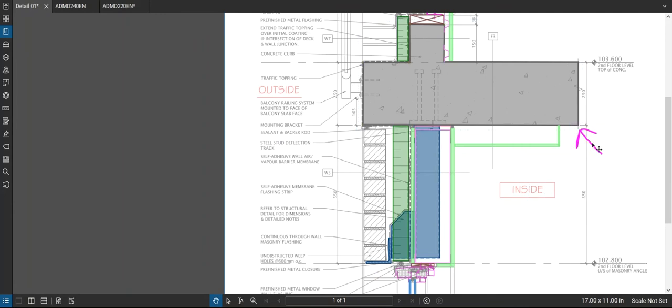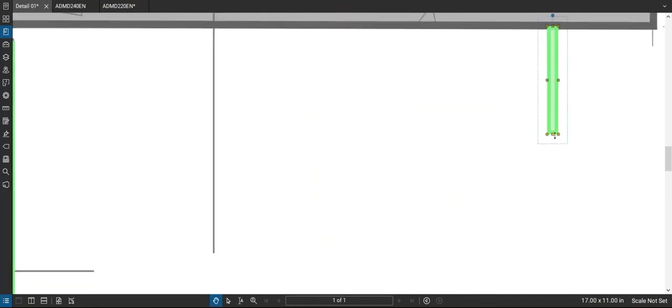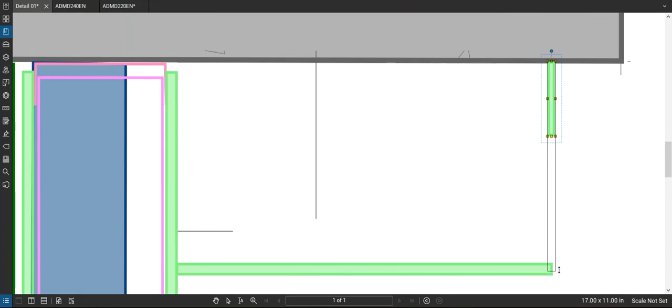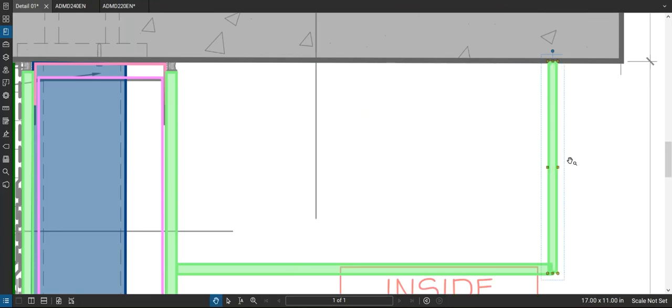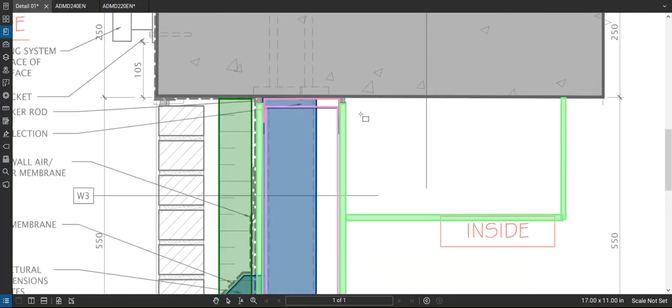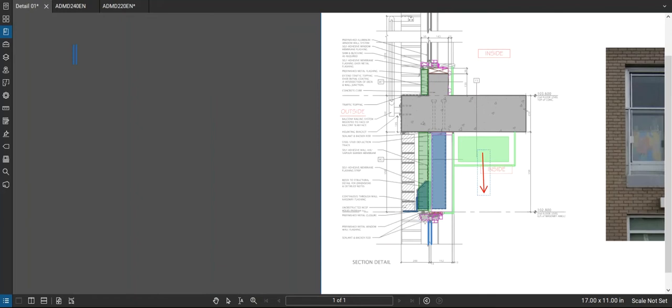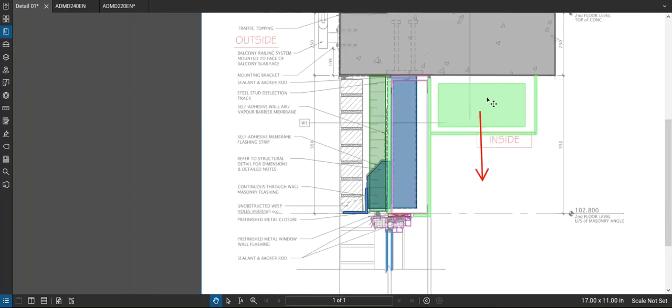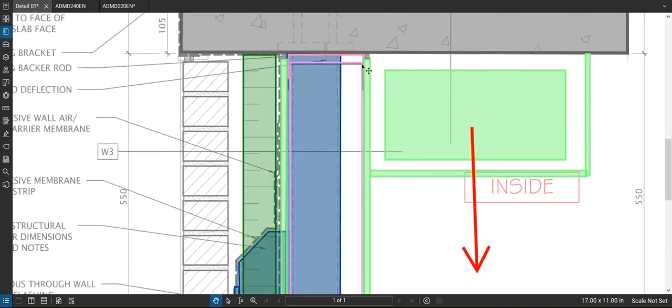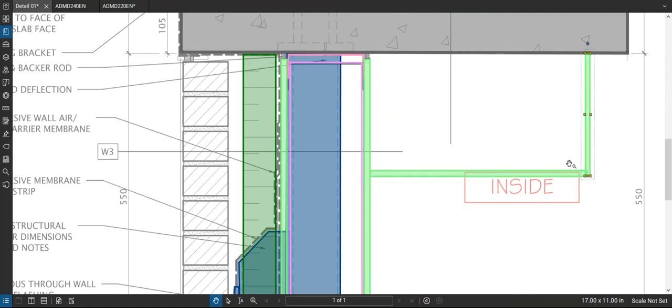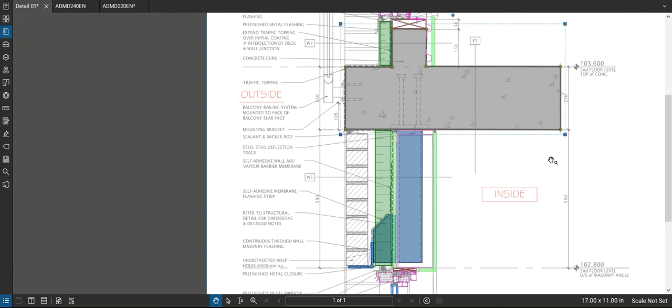Often in these buildings you'd have to take a look at what's happening with the ceiling in here, but quite often on these exterior walls, mechanically you'd have to see what's happening, there's often a duct in here blowing air out in front of the openings. So in that case, maybe there is an opportunity to put some spray foam in there. But again, whether there's a duct or not, I think there are better solutions to that. So let's just delete that.